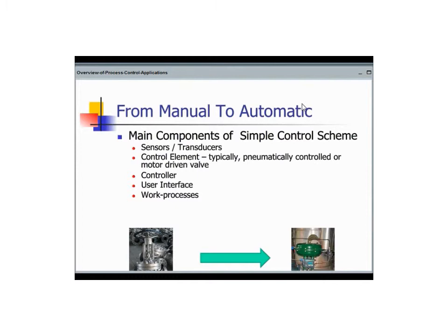The other important development was the control element, which is usually a valve. The change was from a manually controlled valve to a pneumatic, automatic or motor-driven control valve. Here in the picture below, I'm showing a pneumatic control valve. It uses air pressure to move a diaphragm that controls the opening of the valve.